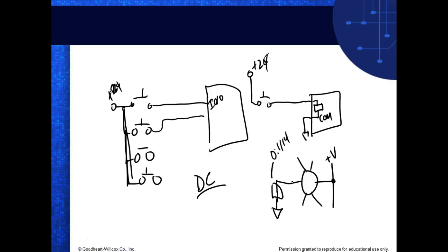How do you determine what module you have? Like, you were looking at those to see if they were sinking. It says right on the front. Every modular PLC I've ever dealt with, it's on the front. You don't have to open up a door or anything. Normally to get the actual model number of the input, you have to open up the door, right? But the sinking and sourcing is actually on the front of the module.